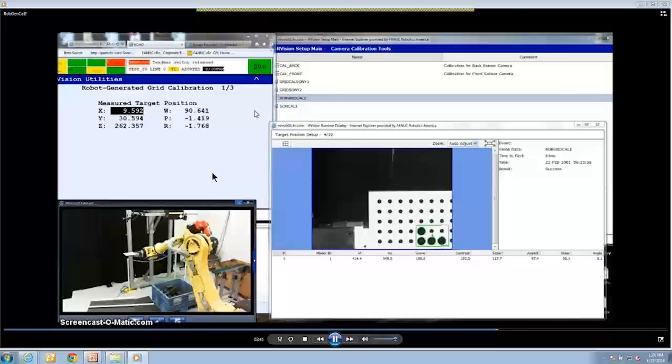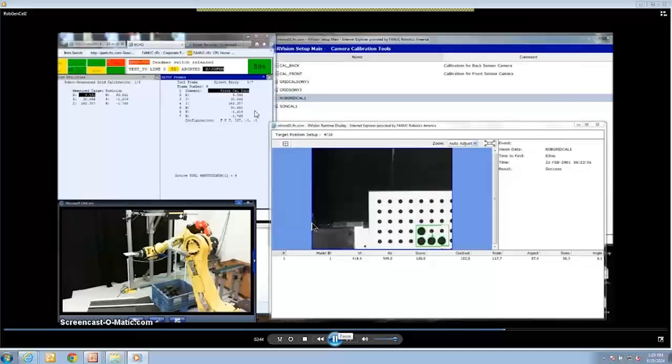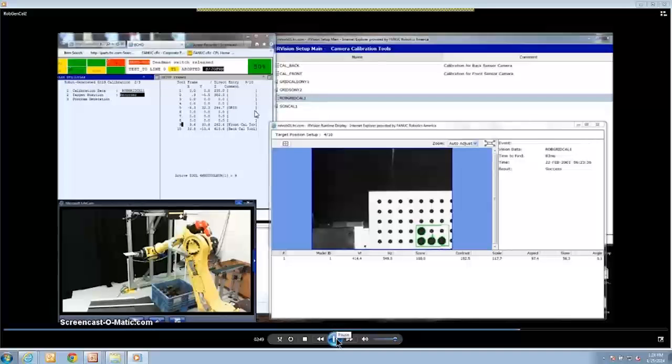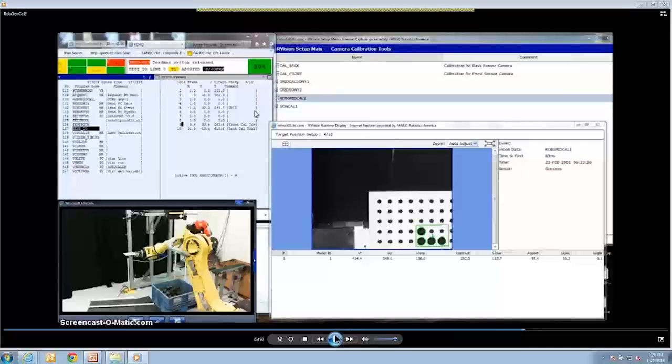So here's our tool frame, and if you navigate to tool frame 9, you'll see that the values it's calculated have been automatically plugged in. So now we did our 2 steps. We calculated our tool frame for our pattern, and we generated a program. So now we're going to run. We're going to navigate to that TP program. It'll be in our select list.